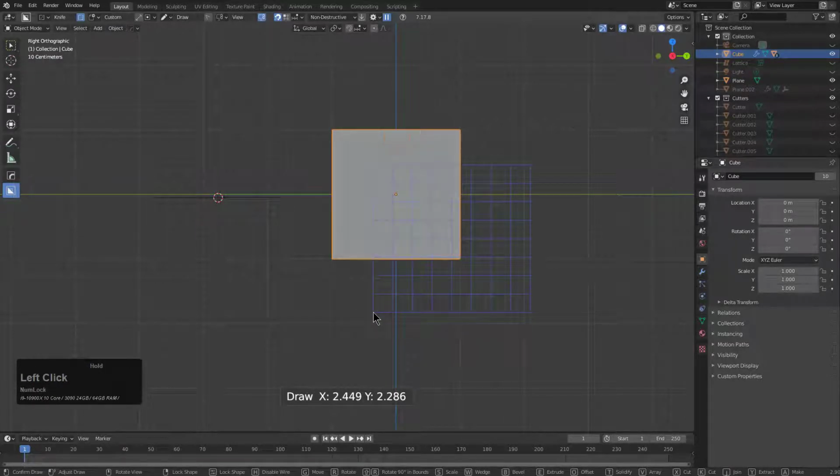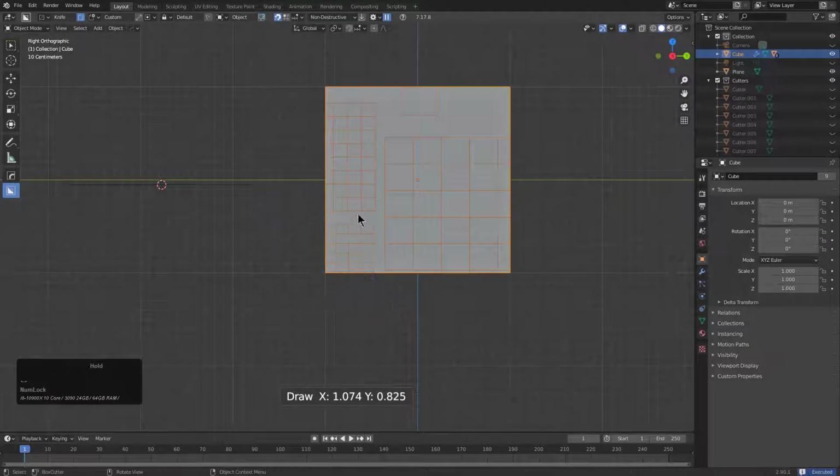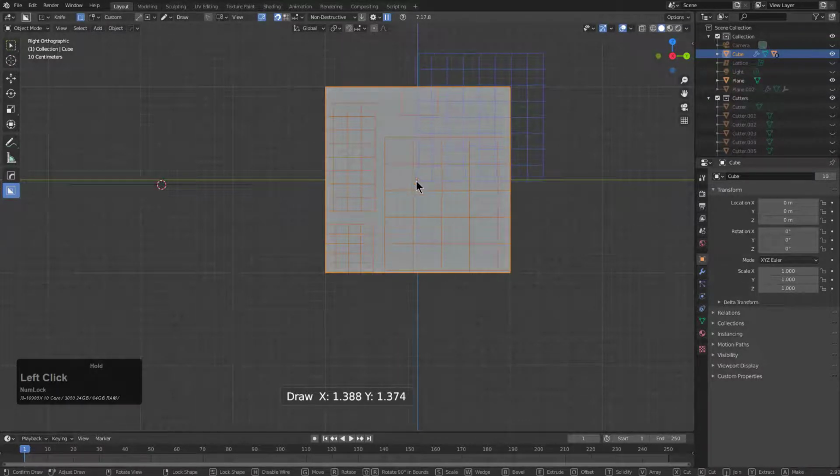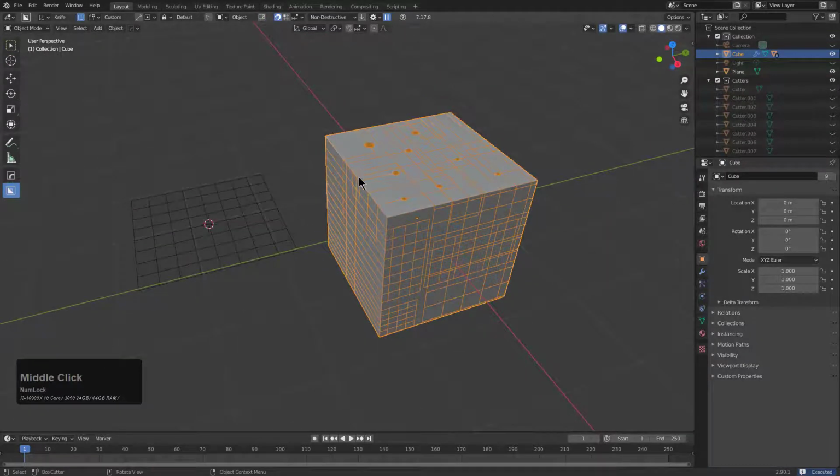So if you start off the mesh or you're working in view align, you can actually use a custom cutter that's actually the shape of something that has no faces, and you'll cut it in just like you see me doing here. So in the event that I wanted to dice a shape using Boxcutter or just cut grids into something, I'm able to quickly do that using the differences between view align and surface align knife.